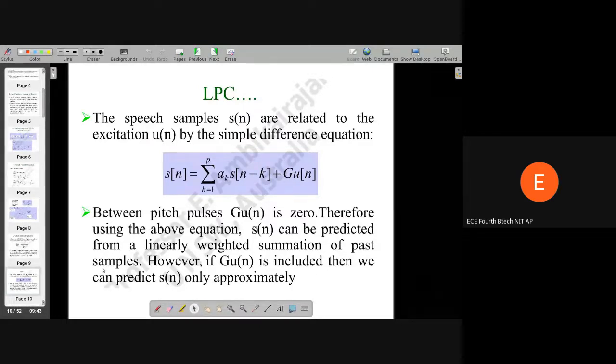The speech signal has a slope, particularly for voiced speech, of -6 dB per octave, and real poles generally cause those spectral slopes. Because of that, we have a heuristic for determining the number of peaks.